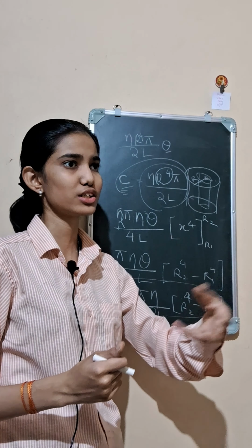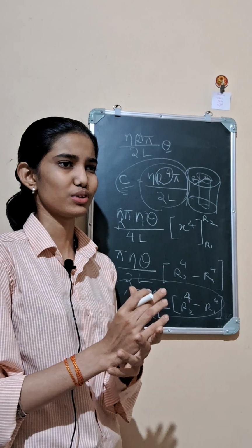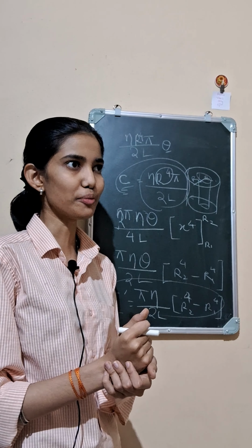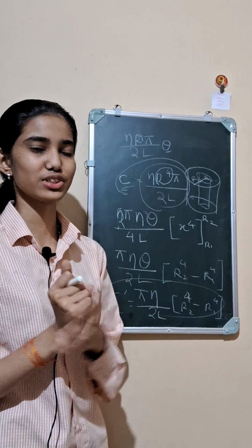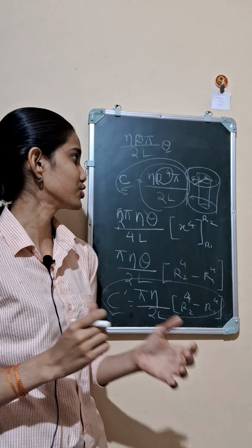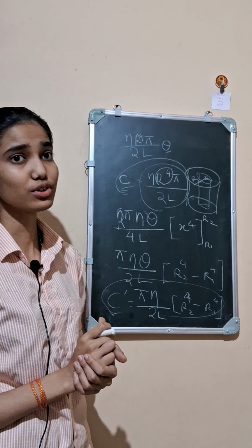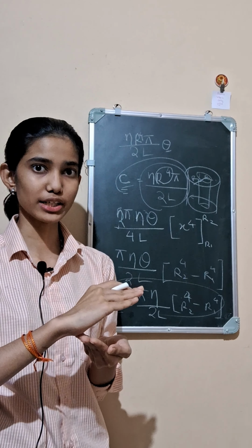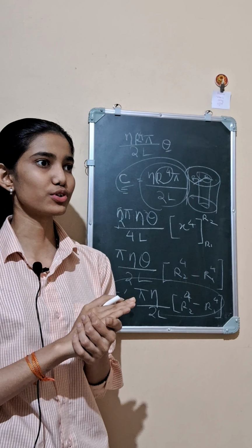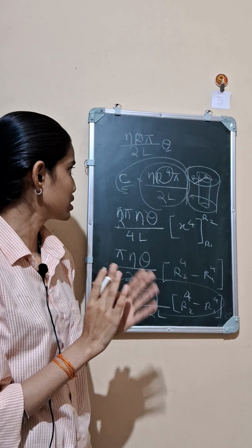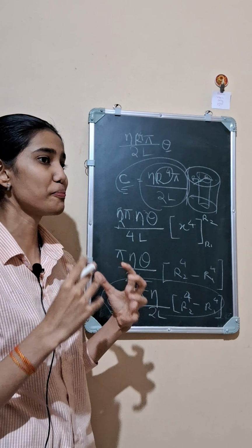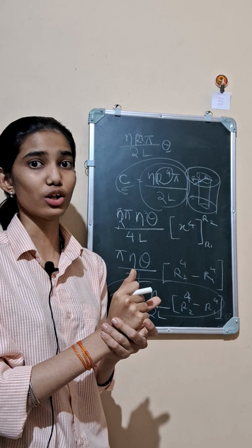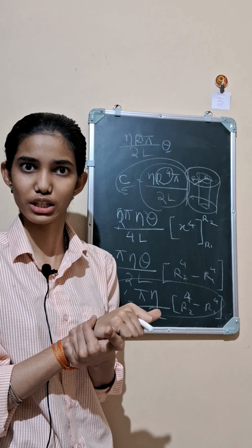If my machinery needs to work with some torque and has to transmit torque, then I will need a shaft, and to get a beautiful shaft, which will work efficiently, I have to calculate the torsional rigidity. I have the mass constant, the material constant, and I am going to calculate whether I should make the shaft of a solid cylinder or a hollow cylinder. The answer is obviously a hollow cylinder.